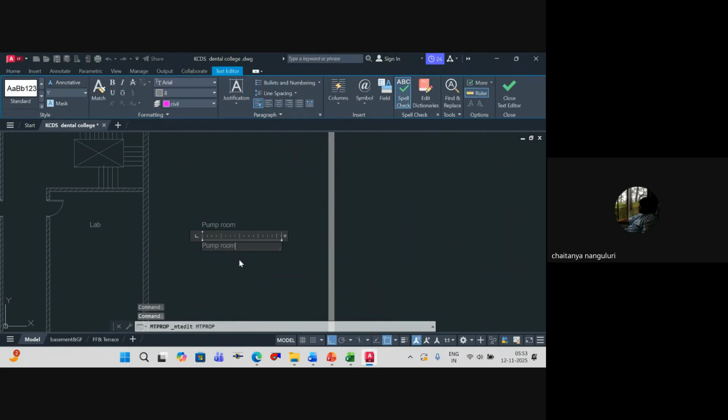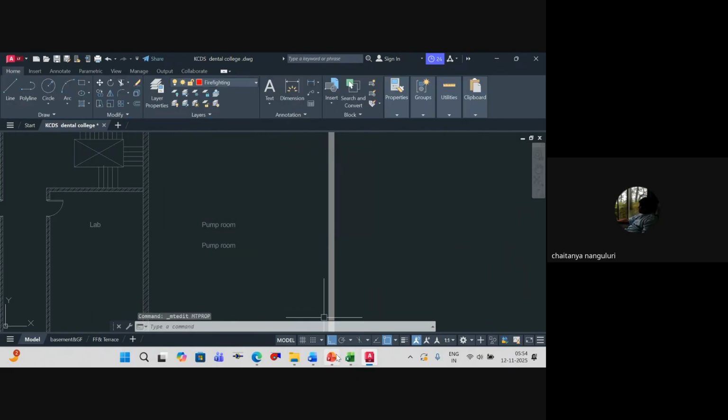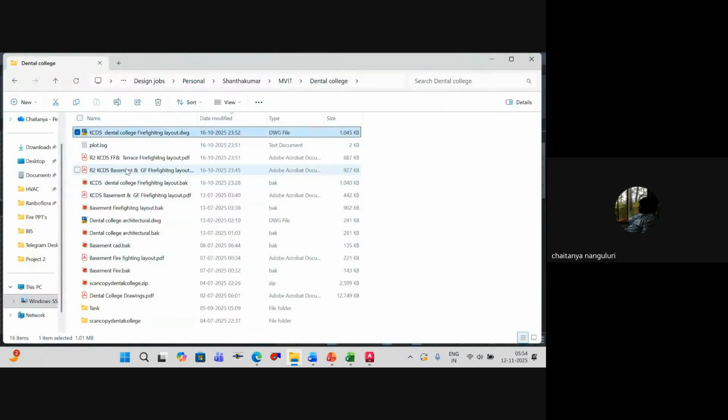And always remember, as per NBC code, of course that will be taken care of by civil, I'm just giving you for information. After around 11 steps, it's mandatory to have a landing. You can't have continuous steps. So every 11 steps, there should be a landing. Exact number 11? Yes, 11 steps, at least you should have a landing. Just a second. So remember roughly.